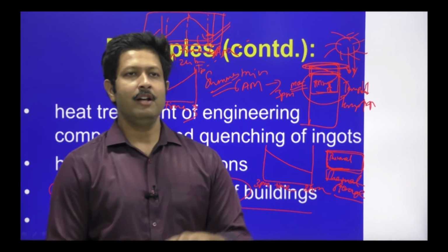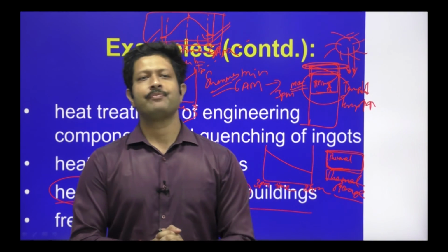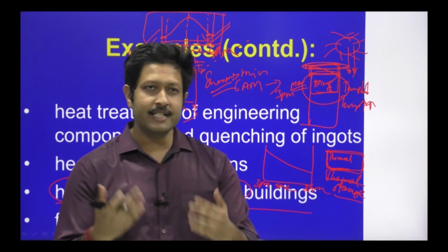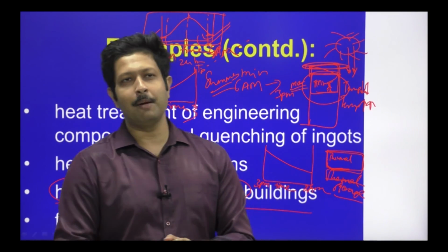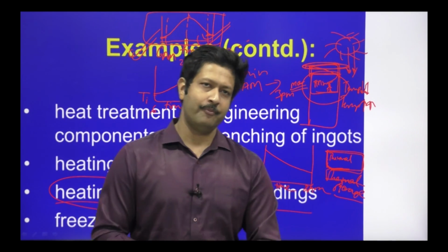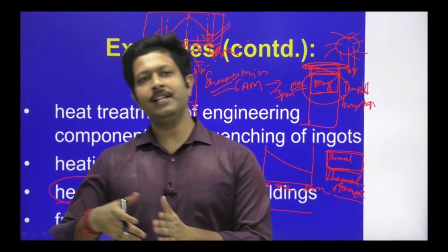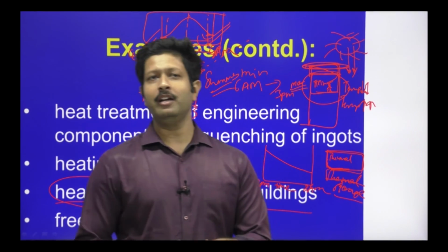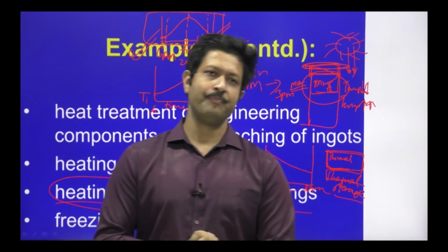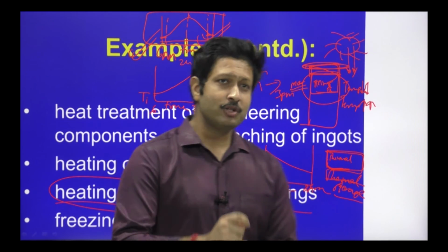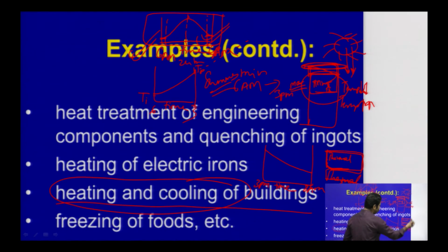And then what happens is, when the night temperatures are coming down, the concrete or the brick has started releasing the heat inside the room. So during the night time you feel miserable, while the night temperatures are settling at a comfortable level outside. Whereas in the daytime, where the temperatures are reaching a miserable level outside, you are in a comfortable zone inside your room. So these two temperature profiles are contradicting each other. This is a new concept that you should know, and this is the thermal storage.